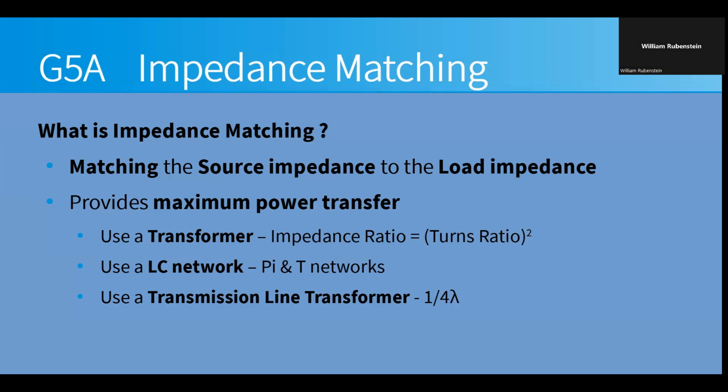You can use like Byron's big black box over here, which is that a pi or an L? I believe it's pi, it's two tuning capacitors. Okay. So some form of LC network to match it, and you actually adjust that to the opposite inductive or capacitive reactance that you see on the load. So it cancels it out.